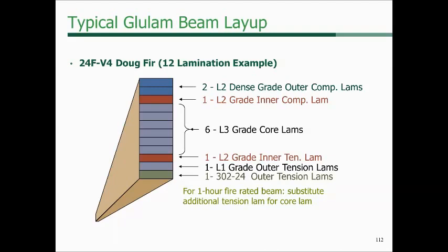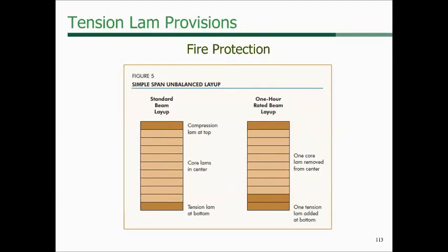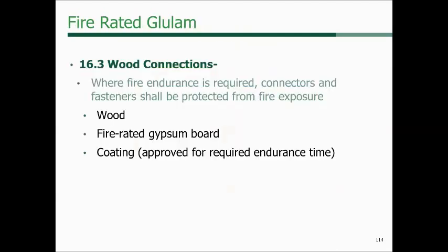And here's another example of what we would need for 1 hour or 2 hours of fire resistance rating. Or this one actually just shows the 1 hour. So that's prescriptively required in the NDS. And there are equations within the NDS that show how to calculate the char depth.